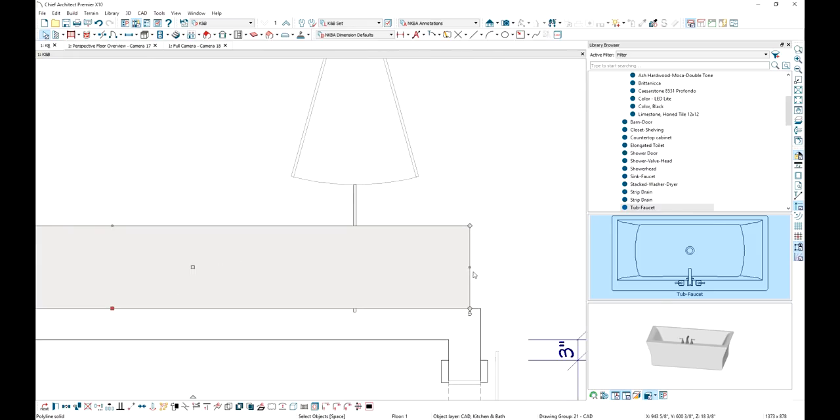While it's still selected, let's grab this edge over here, and with this dimension, let's put in 78.5 inches. That'll extend it out a 1/2 inch, and you can see that this left edge is selected, or the top edge. We'll do the same thing. We'll put it at 12.5 inches. And that should give us a 1/2 inch overhang, and we can go back into the floor plan camera and take a look at that.